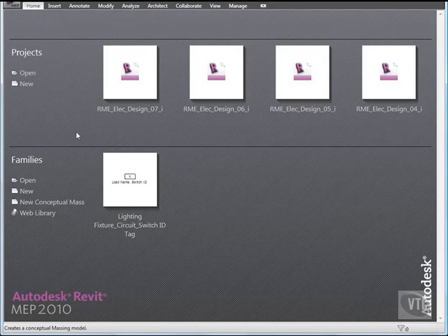In this lesson, you will begin by balancing the loads at the level 1 and level 2 panels. Then you will examine the loads presented at the panels to set your final breaker sizes. And finally, you will verify and adjust wire sizes that Revit MEP recommends for handling the loads on those circuits.